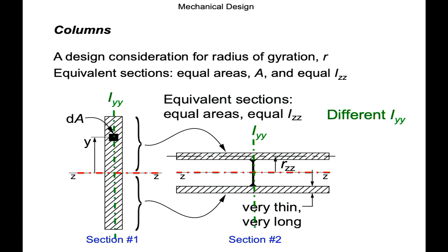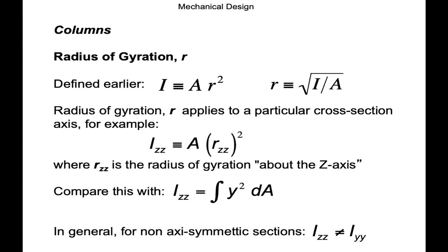You can see just by looking, we've got a very different second moment of area in the Iyy direction between the pair of them. And by analogy to the ruler that I'm waving around, it only ever wants to elastically deform in one direction. It never deforms towards you or towards the board, because the second moment of area is so much higher in that direction, as per that radius of gyration. Same essential process.